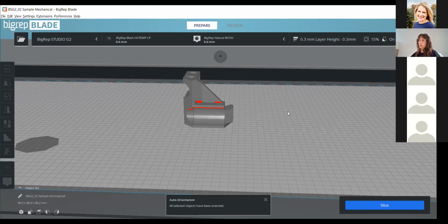Obviously, with this option, you're going to be able to print a lot fewer parts on the print bed, as you need a lot of space around for the gantry to move and not crash into the finished part. The other option is to fill the entire print bed up and print all at the same time. Essentially it would print the first layer of each part, then the second layer of each part.